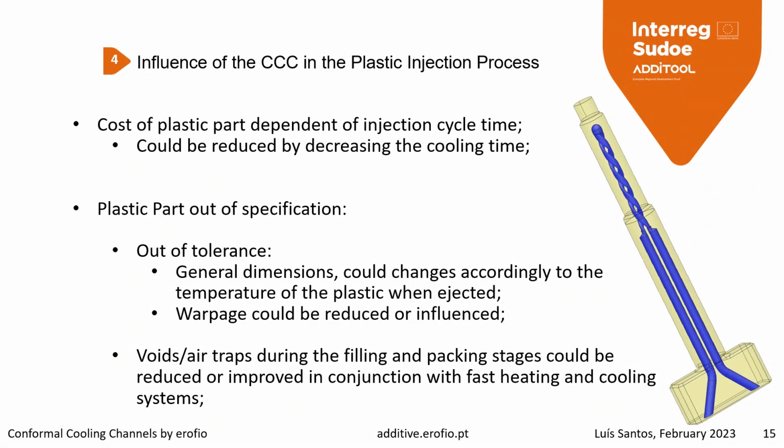Voids and air traps during the filling and packing stage could be reduced or improved in conjunction with other kinds of systems with fast heating and cooling. For example, we can use porous steel to remove this kind of problem from the cavity.